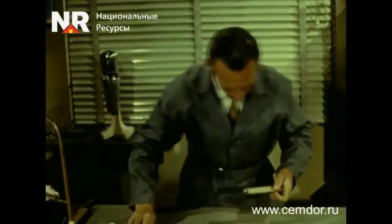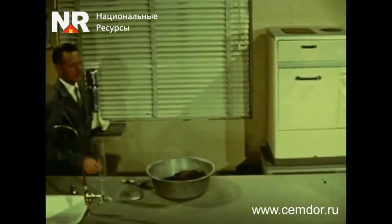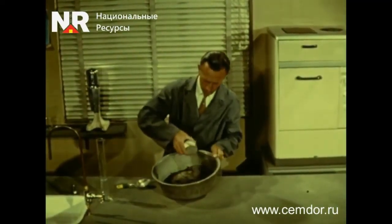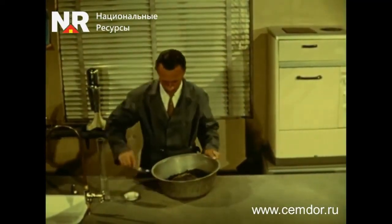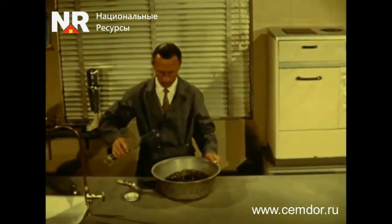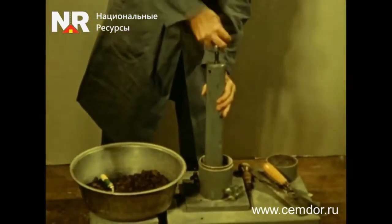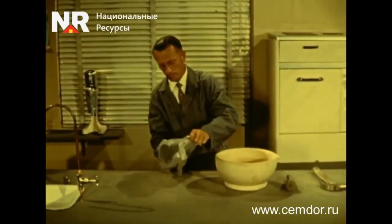After determining the physical and mechanical characteristics of the original soil, it is necessary to assess the effect of various additives in cement on the properties of the stabilized soil. For this, the soil and a small amount of cement, possibly together with the stabilizer, are mixed, water is added, samples are molded, and they are left for 7 days. After that, the samples are broken up, crushed, and the changes are determined.